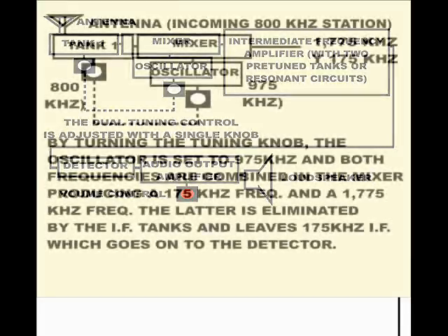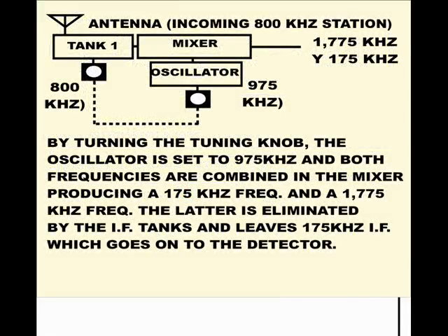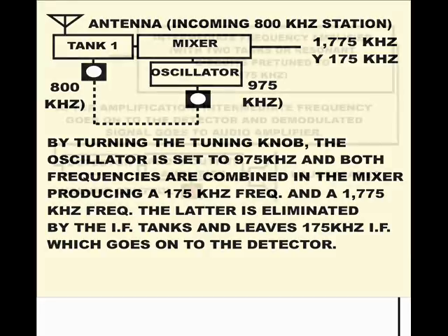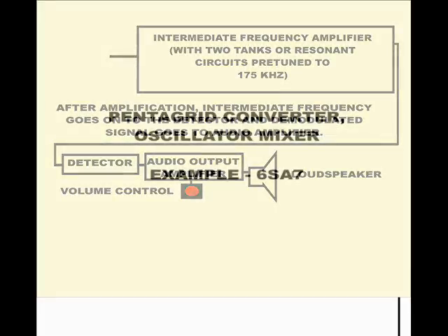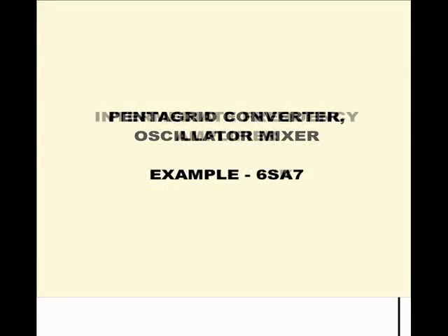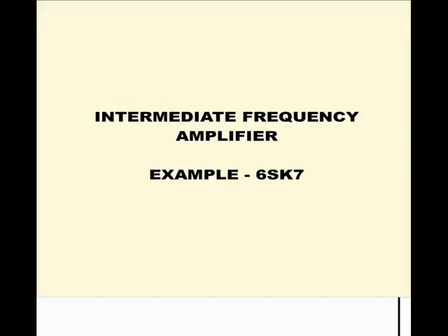So if you wanted to tune in a station with a frequency of say 800 kHz, kilocycles per second, the frequency changer would convert the signal to the receiver's intermediate frequency, usually 175 kHz, and from there on the radio would amplify it to a suitable level for filling a big room without any further adjustment. Vacuum tubes evolved with new improvements, from the original triode, the first amplifier,